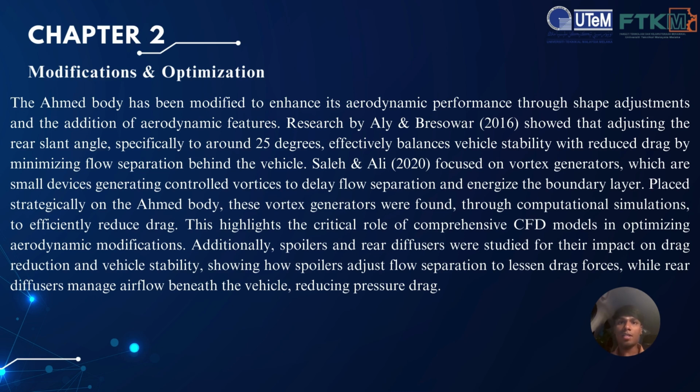Additionally, spoilers and rear diffusers were studied for their impact on drag reduction and vehicle stability, showing how spoilers adjust flow separation to lessen drag forces, while rear diffusers manage airflow beneath the vehicle and also reduce pressure drag.